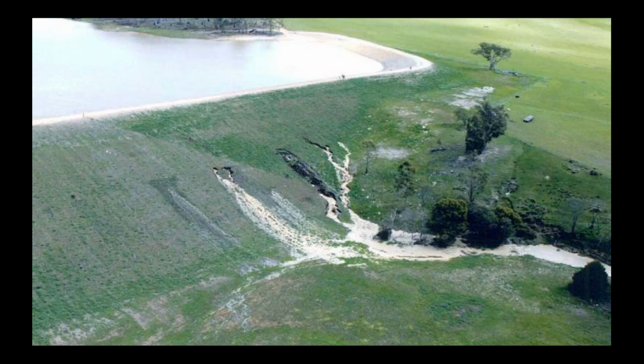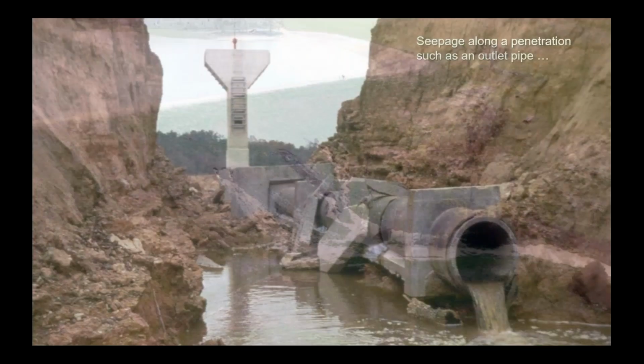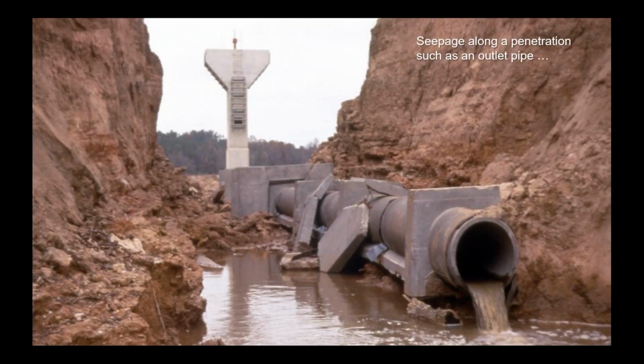And what you see in this picture is uncontrolled seepage. You know it's uncontrolled because of where it's coming from the dam, what it's doing to the dam, and also by the color of the seepage. It's brown, so it's picking up embankment material, it's eroding it, and it's just a matter of time, and this dam is going to fail. So it's important to know how the dam was built.